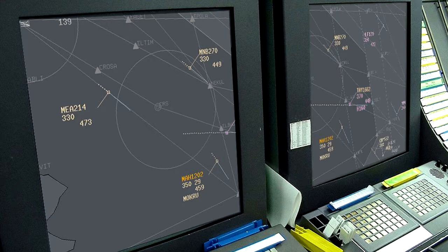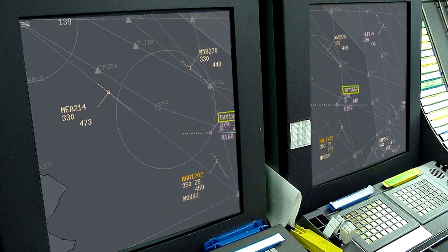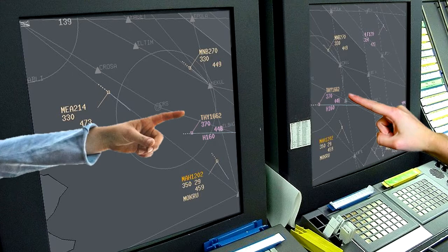The methods used to transfer radar identification are: designation of the radar position indication by automated means, provided that only one radar position indication is thereby indicated and there is no possible doubt of correct identification; notification of the discrete code of the aircraft; direct designation, pointing with the finger, of the radar position indication if the two radar displays are adjacent, or if a common conference type of radar display is used;